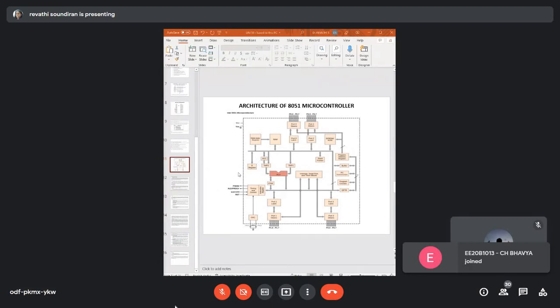Next is your B register. The B register is again a special 8-bit math register. It is also bit or byte accessible, so you can access individual bits or the whole 8 bits at a time. That is your bit or byte accessible. It is in conjunction with the A register, as it can store one of the operands for the ALU. It is again used as a general purpose register to store 8-bit data.